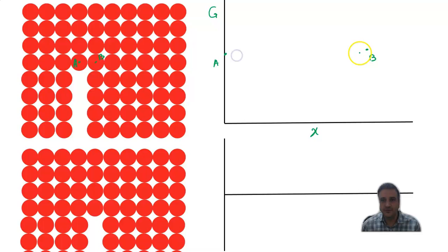The energy state of the dislocation in these two positions is minimum, but when the dislocation moves from left to right, we have an increase in the energy of the dislocation because of the breaking of the atomic bonds. And in the final position, when the dislocation reaches the B position, its energy reaches its lowest value again. When the dislocation moves from this side to this side, it is as if this plane moves from right to the left. We have also some forces on the dislocation.